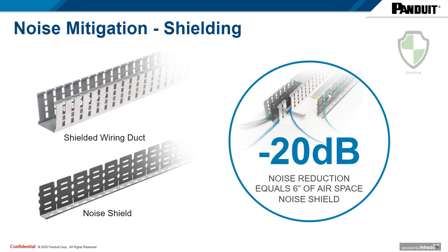While distance separation can be an effective strategy to separate a few runs of commercial grade Ethernet cable from other wire classes, it becomes more difficult as the number of connections increase. Sometimes design or space limitations don't allow sufficient segregation of equipment and cables, and other solutions such as shielded cabling must be utilized. This can obviously add significant cost to the design.